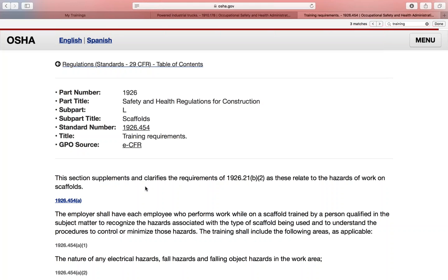Okay, and of course our PPE. The third bullet point there is use of personal fall arrest equipment, a body harness, lanyards, as required for the type of lift being used. Okay, and we have to have approved anchor points, and I'm going to show you some examples of those, of the body harness and/or lanyard and/or body belt, in just a moment. Also, do not use an aerial lift on uneven ground. Lower the lift and lock it into place before moving the equipment. Also, lower the lift, shut off the engine, set the parking brake, and remove the key before leaving it unattended. And then ultimately, stand firmly on the floor of the basket or the platform.